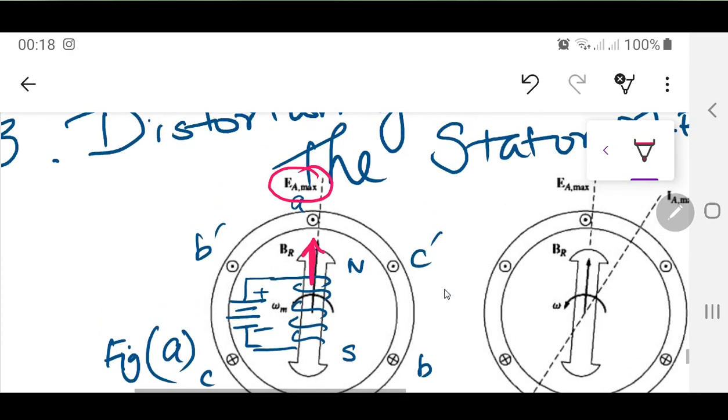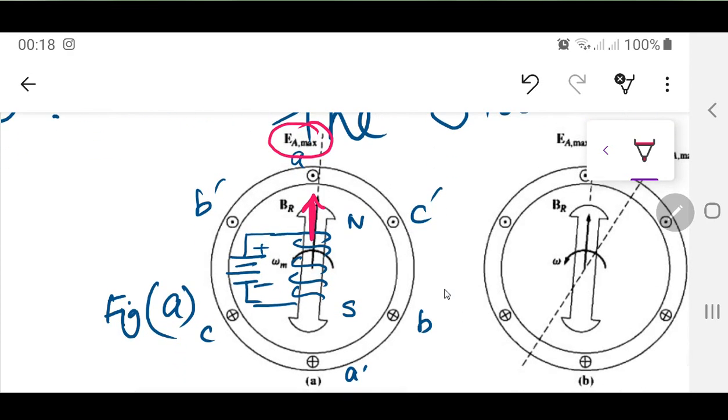Now in this machine, suppose it is not connected to any load: the A dash, B dash, C dash three-phase windings are not connected to anything. This means that your V phase is exactly the same as this. Why? Because when the machine is not loaded, your V phase, which is the terminal voltage or output voltage of that generator, and please remember, when I use the word V phase, this is actually the phase voltage here.